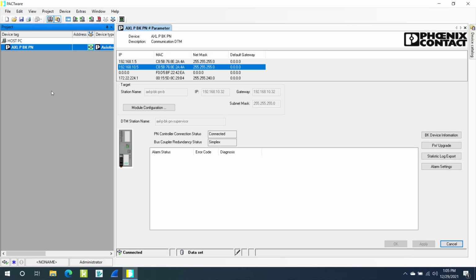First step is connecting to your system, parameterizing it, configuring all your HART sensors and your IO, your sensors on the system, and then the next step would be to use a tool such as Emerson AMS or Yokogawa PRM to perform the actual asset management of a network. So we're just going to show the HART data that you can get through a freeware tool such as Pactware, FieldCare, etc. Basically, in this scenario, we're just using Acyclic P.